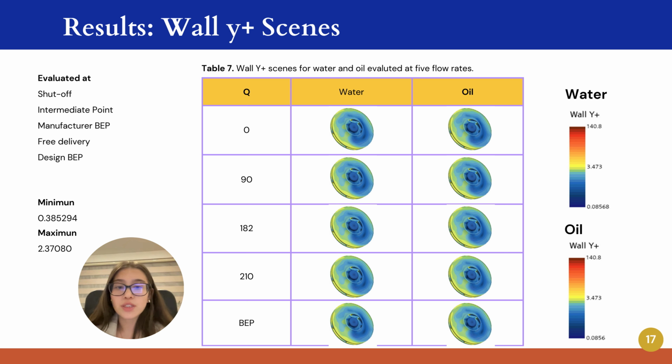In conclusion, the objective of the project was successfully achieved as the centrifugal pump was efficiently modeled using both CAD for the design and CFD for the performance analysis. The simulation confirmed the inverse relationship between fluid viscosity and pump efficiency noted in the literature, as the pump showed higher efficiency with the water than with the oil. A thick mesh independent model was determined to be the most suited for balancing time and efficiency in the simulations. Additionally, various dimensionless numbers such as the Reynolds number were calculated to ensure accurate representation of the simulation models.